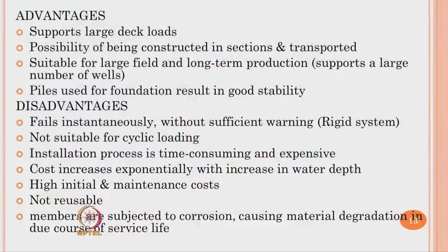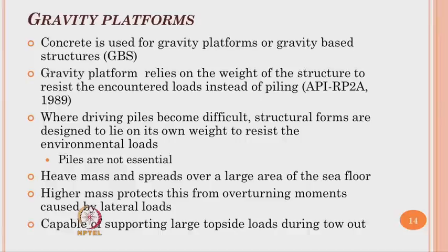Since they are founded firmly to the sea floor, decommissioning the platform completely is impossible. Therefore, the majority of the substructure becomes non-reusable. The members are subjected to corrosion, which can cause material degradation in due course of the service life, and that will also decrease the strength of the members.